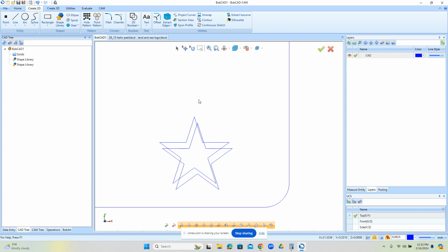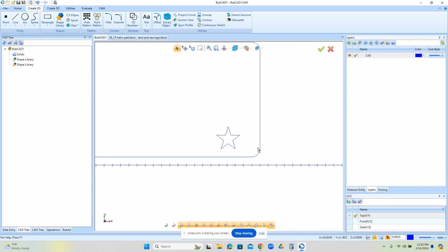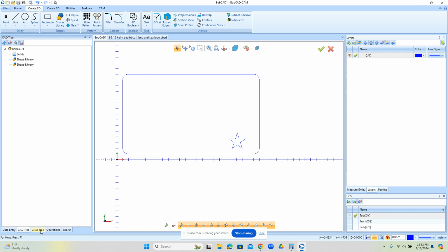Okay, so how do I do that? I'll go to select mode here, left click 1 time. Then I'll come over the edge, or the one that I want to delete. I'll hold down shift, then I'll move my mouse over it. It highlights one edge. I'll left click. Okay, then it selects the whole thing. I let go of shift. I can move my mouse around. Now I can hit delete, and then it will go away. All right, so that's our logo, and then we have our profile.